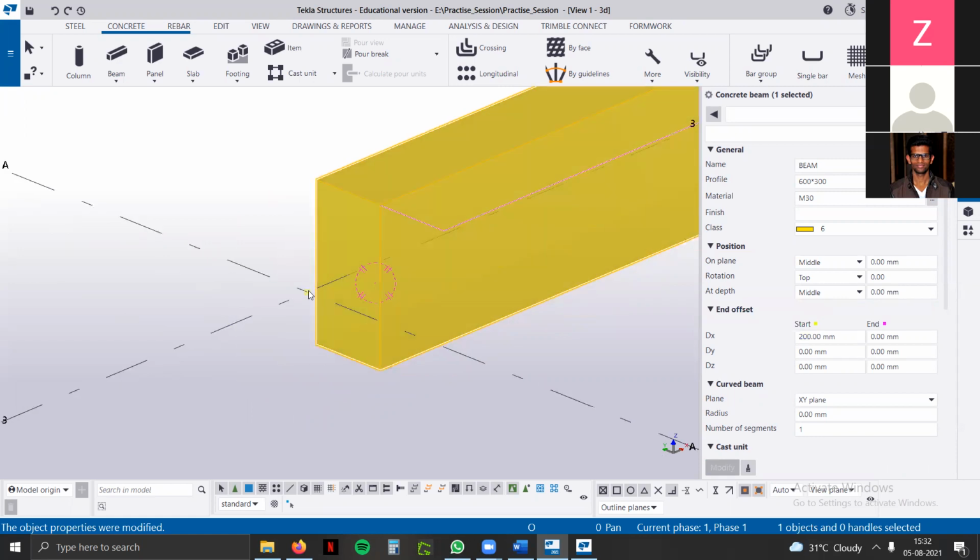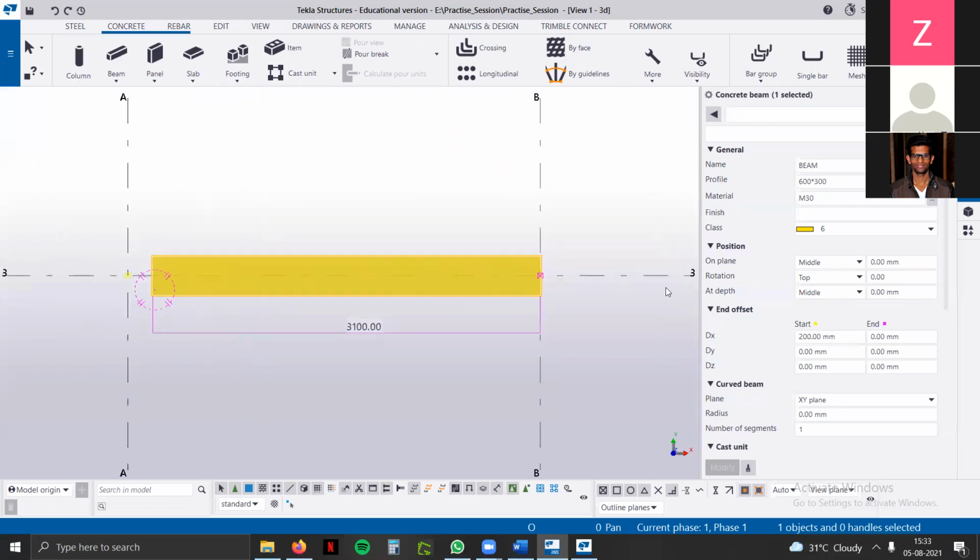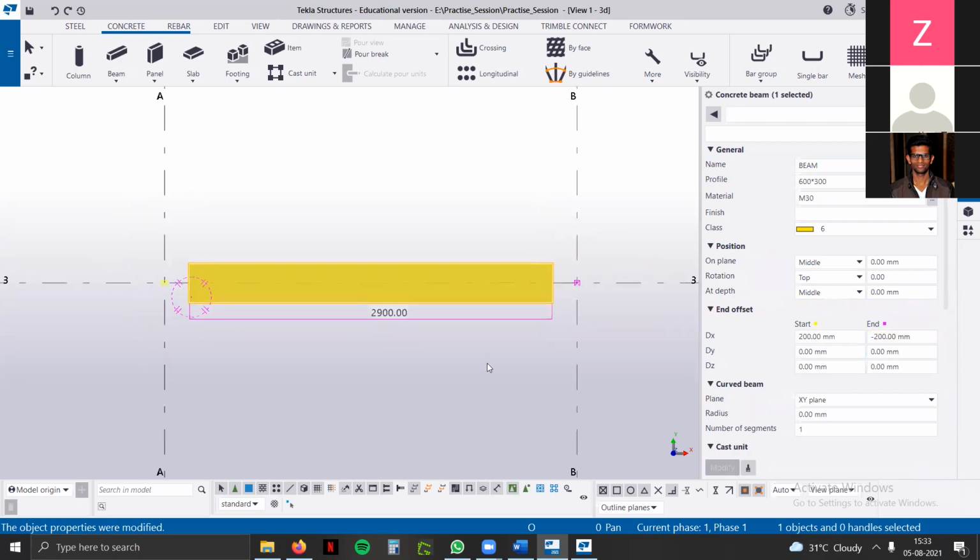So offset is like removing some distance or moving it by a distance from this part. So it will create some gap from there. And if I add a distance again at the end, it will move. But if you want to make it go backwards, what will you do? We'll add a negative to it, so it will move backwards. So the minus sign helps us reverse the thing, and for positive you don't have to give a sign, but it moves in the positive direction.